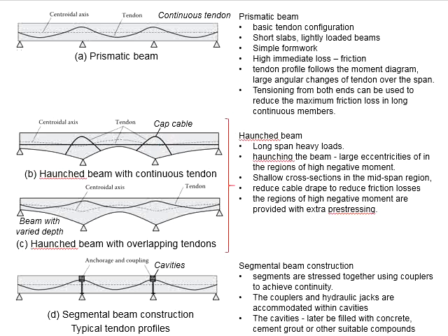Through this, we can foresee that the amount of frictional loss can be minimized, and this kind of design is advantageous for long spans with heavy loads, where you require a higher degree of eccentricity to generate sufficient resistance from the prestressing force.